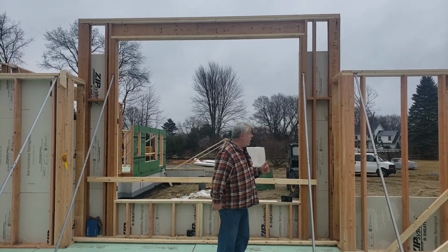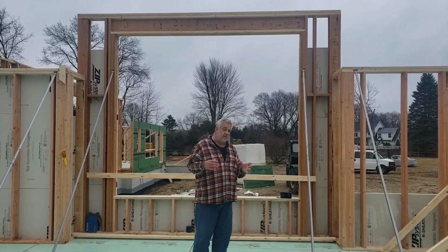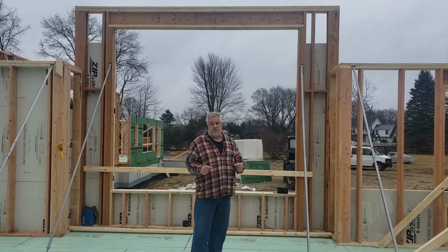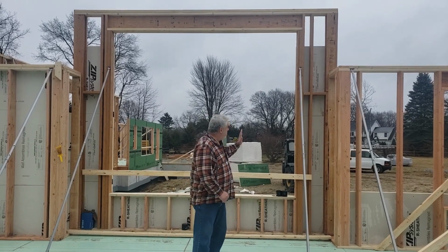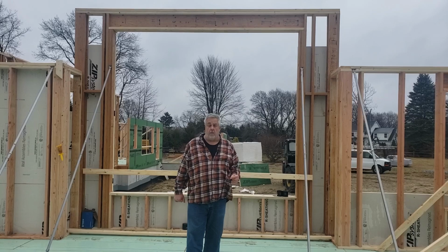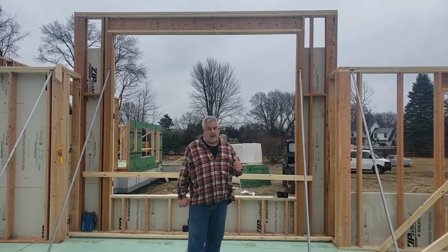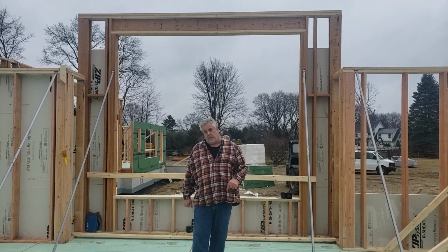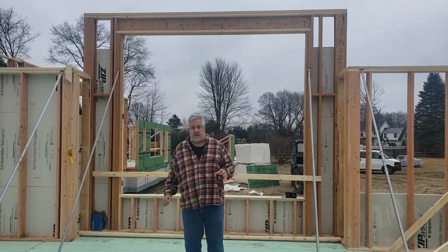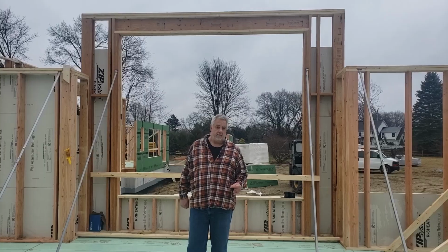That makes for a little sturdier of a wall, a little more consistent. They're less likely to twist and warp, so we can maintain the geometry of that rough opening so the window fits in there nice and neat. So anyways, that's the 3 windows. Let's go back to the studio. We'll break out some details, some drawings, and we'll talk a little bit more about window rough openings.